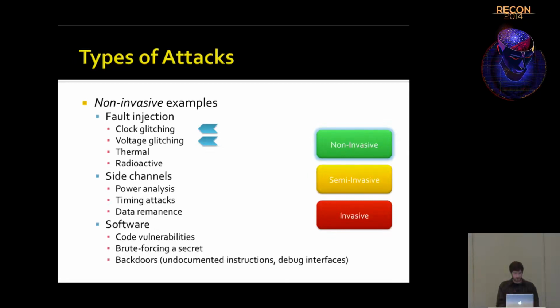And so kind of a point there is memory zeroization is something you have to be aware of. Most chips that aren't security designed or purpose built may not wipe RAM or other volatile memory in response to certain conditions, but some may. So that might be a consideration that works in your favor if the device, upon reset or halt or whatever, doesn't actually wipe its memory. Then there could be some goodies still left behind.